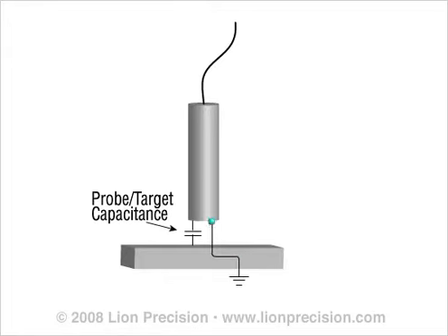For sensing current to flow, it must find a path to ground. Anything that resists the current flow to ground can interfere in the measurement. Therefore, the effect of using an ungrounded target depends on the alternate path the sensing current takes to ground and the amount of resistance it encounters along that path.